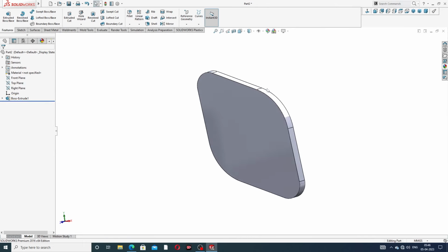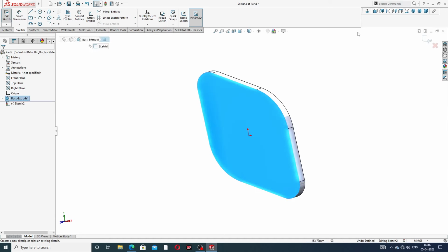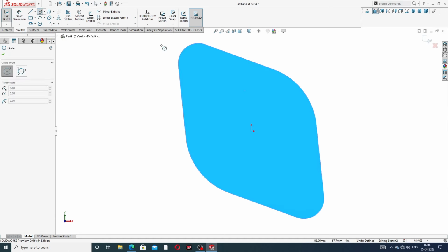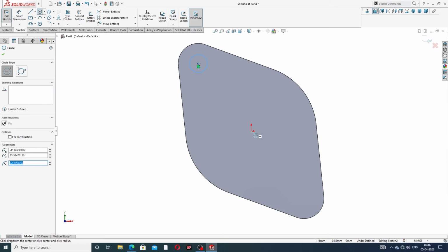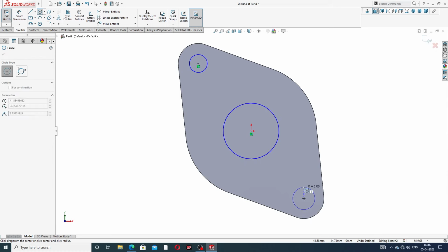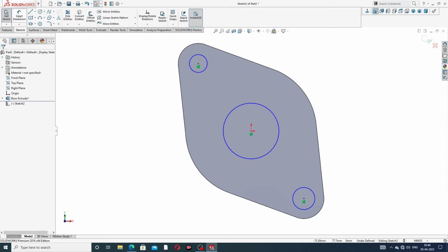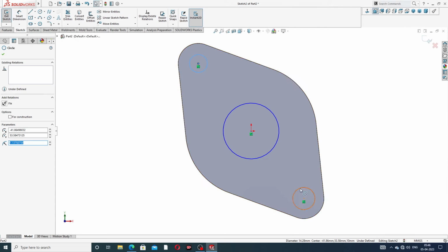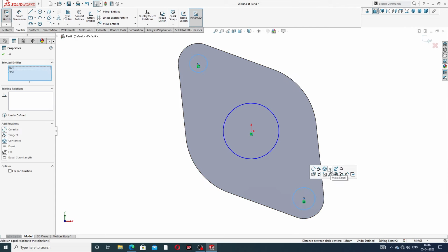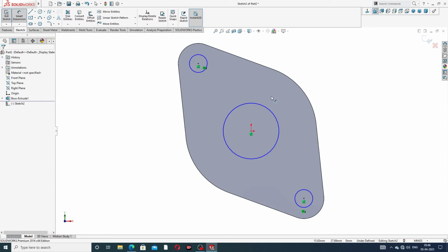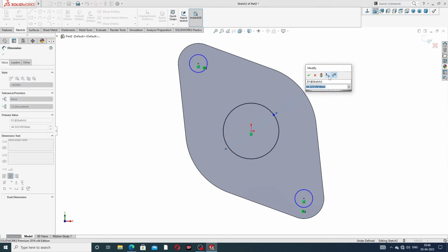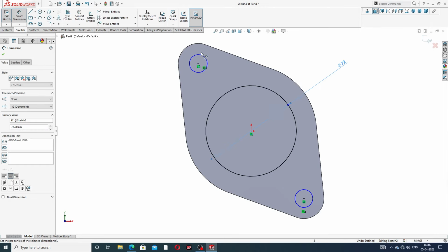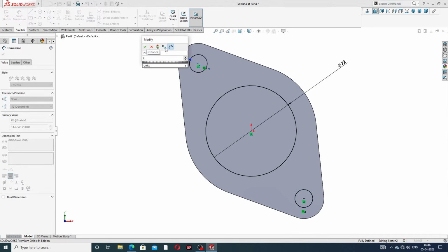Okay, this is very nice. This face is also sketch normal, and draw a circle, again a big circle, and draw a small circle because this is a cutout. Click both circles, press the Control button, and set them equal. This is 72 millimeter, and this is 17 millimeter.